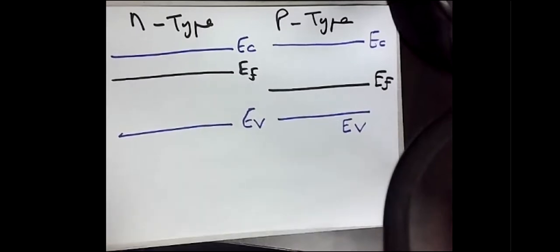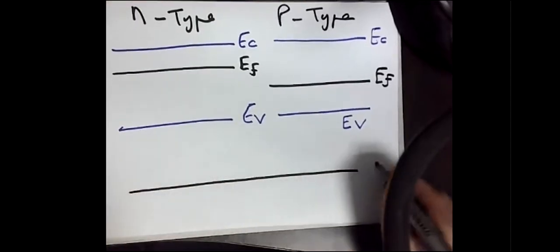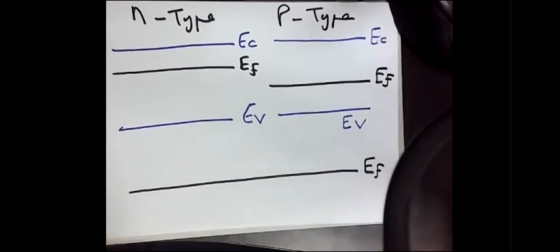What we are going to do, simply, my dear students, is first plot a horizontal Fermi level. And if you remember our first lecture, you will be quite sure why we plot this as a horizontal line. This is because this p-n junction is under thermodynamic equilibrium. I mean, we did not put any type of external bias on this p-n junction. So its Fermi level should be totally horizontal. This is typically what we learned in the first lecture.